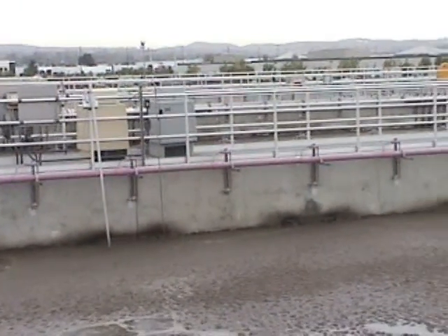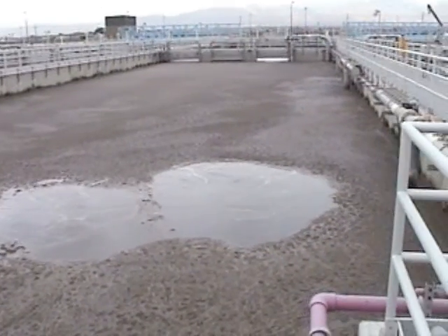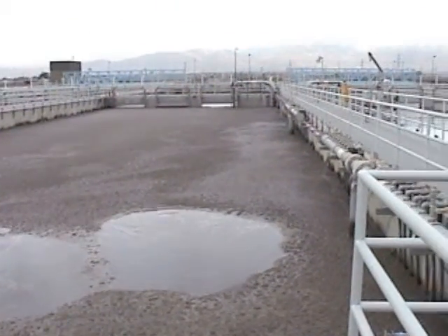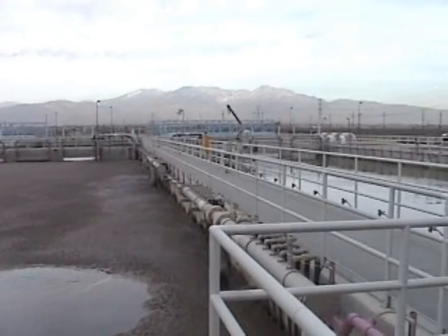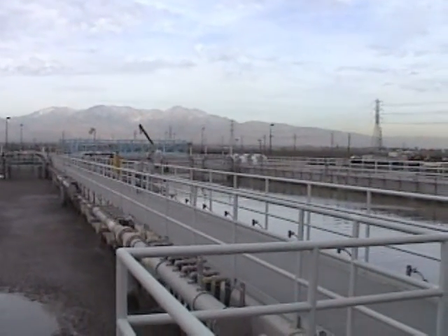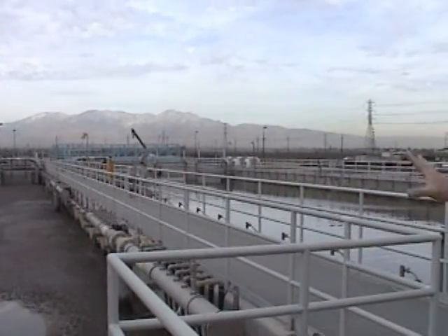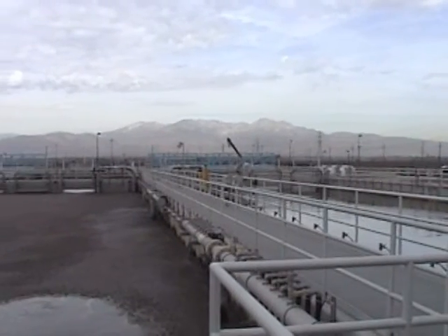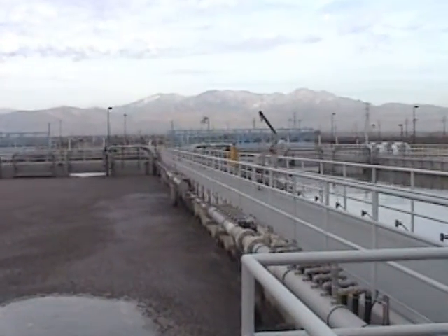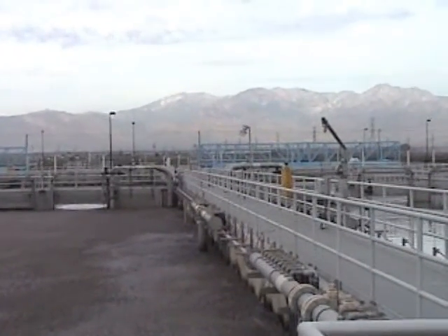We should have a set point. The system pressure here at RP5 is 10 psi at the blower, and I'll show you on the SCADA system where you can see that. And we will increase that. Sometimes we'll go to 10.5. But at 10.5 psi throughout the system, you should be able to achieve adequate DO throughout the whole basin. And the valves at that point should not be 100% open.